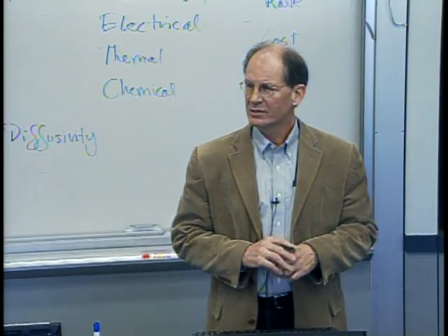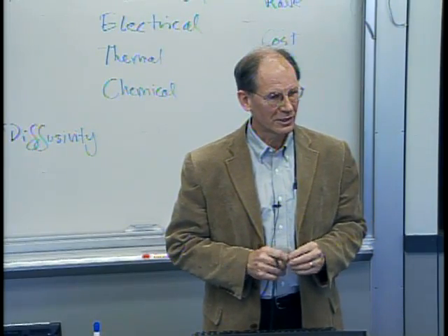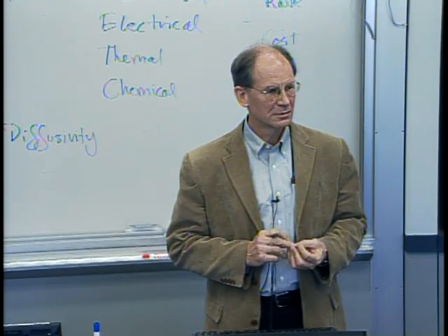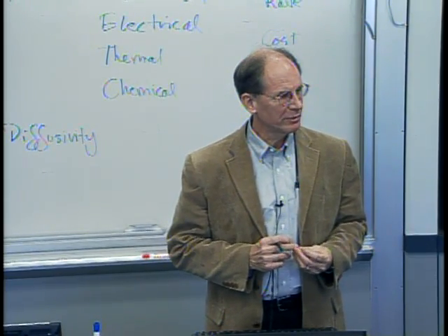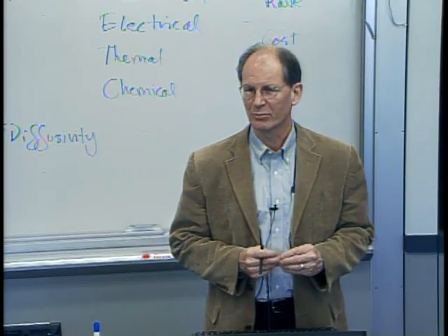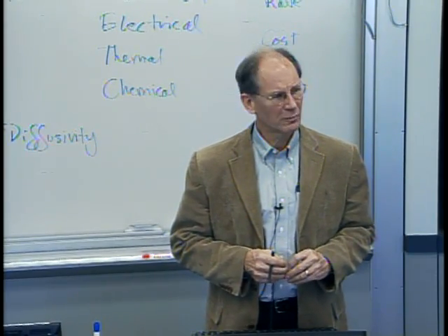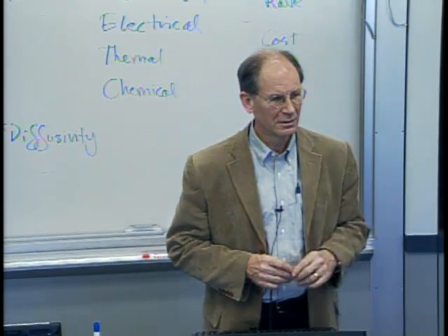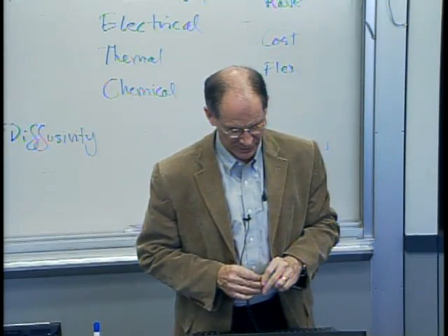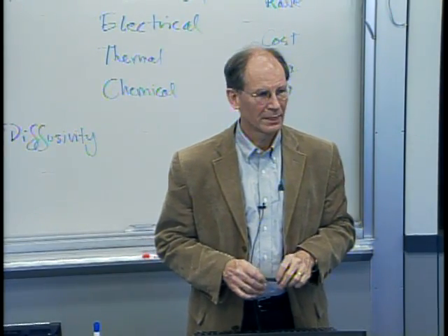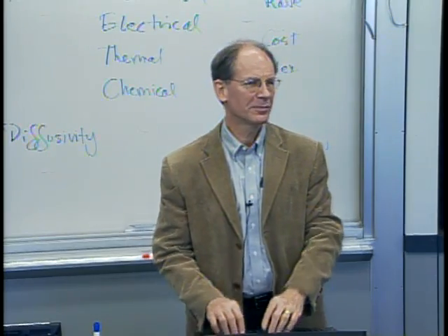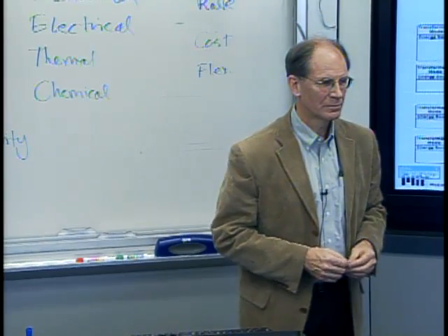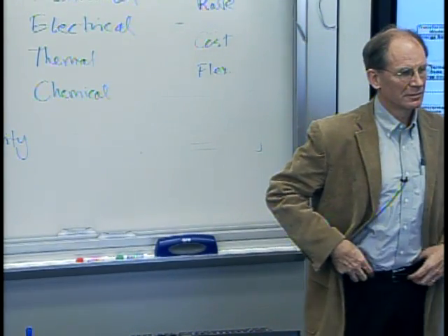Oh, just because I always like to do this. Stereolithography, how does that work? It was the original rapid prototyping process, I think. Anybody know what the trade name for that is now? That's the most commercial of them. There's a machine right down the far end of this hallway in the architecture department that's an STL machine. Stereolithography? I guess it's become passé now. Yeah, Adam. I don't know what the liquid is, but you selectively harden that liquid material with the laser, and then it goes down.